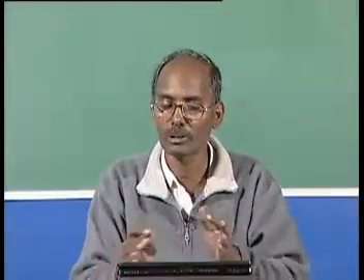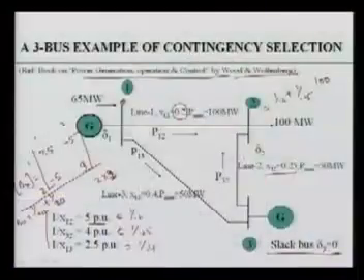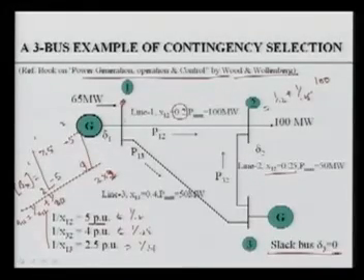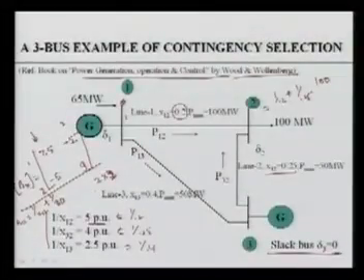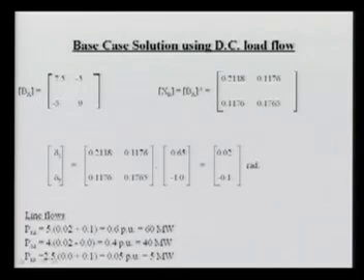Without any doubt, you can create it even though your system is large. Suppose several lines are there, so keep on going in the same way. You have to see the diagonal element for bus 1: it will be the sum of all the admittances of the lines connected at bus 1. For 2, it is the sum of the admittances of the lines connected at 2. Now for the off diagonal elements, if you are talking about 1 and 2, then you have to take the negative of the admittance between bus 1 and 2. That I have written here, and similarly you can keep on going to form this. So this is your Bx matrix, which I have written also here.